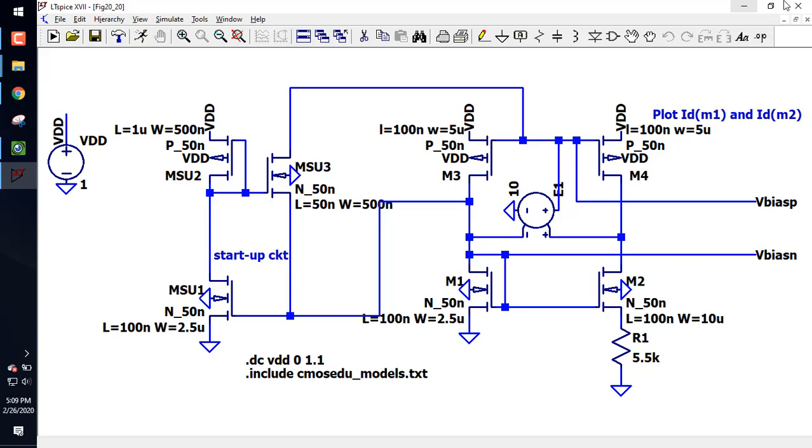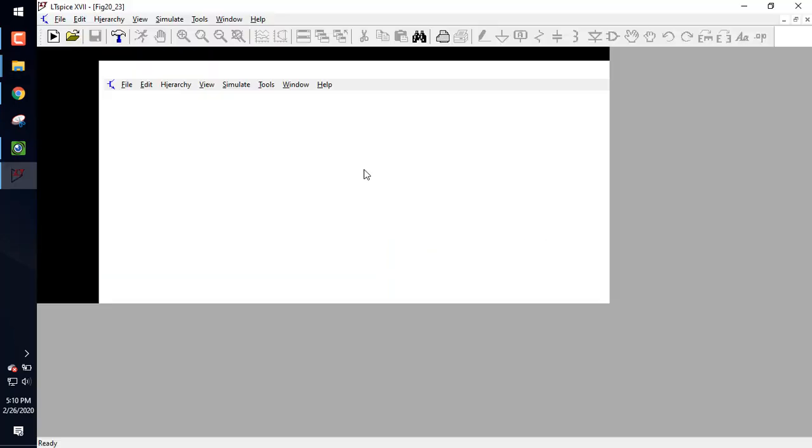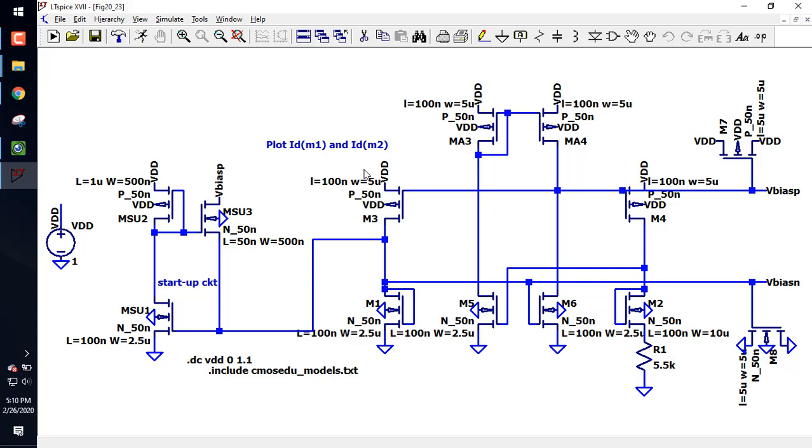So let's go replace that, and let's look at the circuit. Here you see the amplifier, but I did something a little different to make it even more stable. I gate-drain connected this side, which I had before. I broke the loop between the two because I'm holding them the same. Then I gate-drain connected this side. So the amplifier, if this is VGS1, will try to keep this side at VGS1 as well. So what's this voltage? It's VGS1 minus VGS2 over R1.